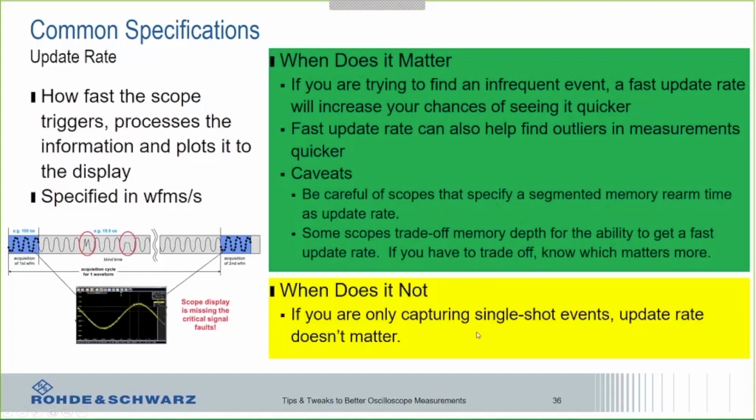So when does fast update rate not matter? If you're only capturing single shot events, update rate doesn't matter at all, because you're only capturing one waveform.